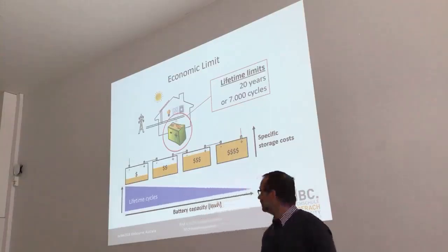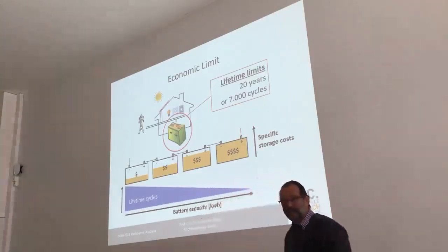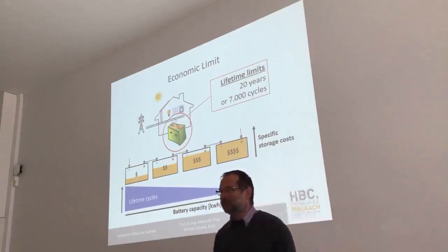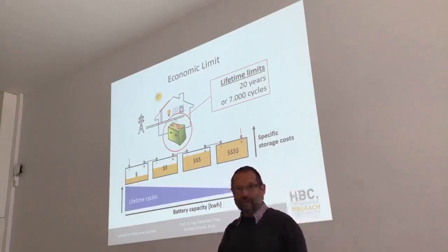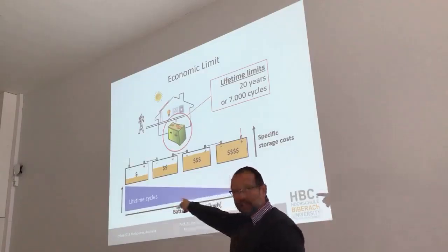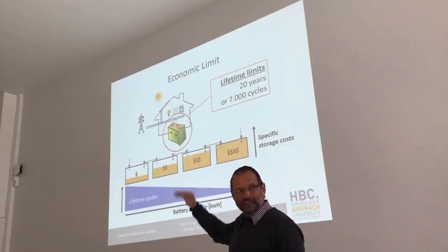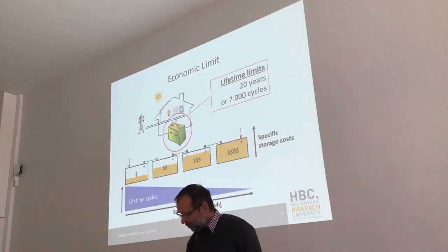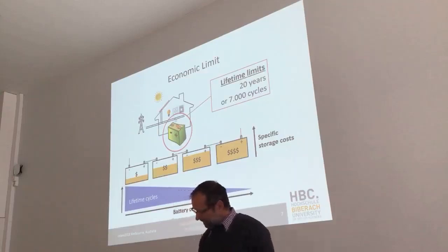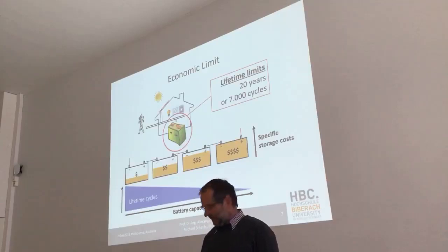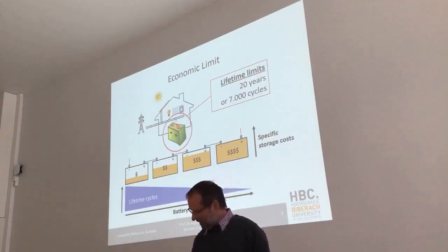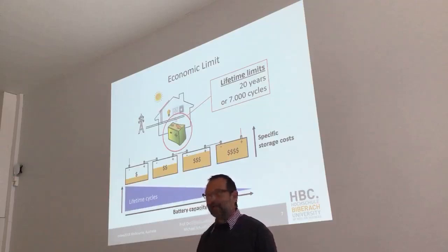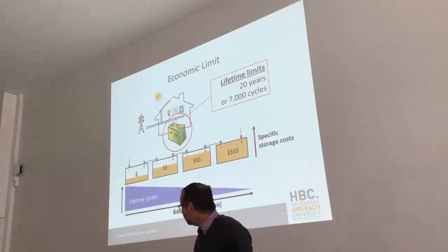Imagine a battery as a sum of battery cells charged and discharged after the principle first in, first out. Then the first cell on the left-hand side passes through much more charging cycles than the last cell on the right-hand side during a given period of time. Since the economics of each battery is influenced by the real charging cycles of each individual cell, the term full charging cycles of the last battery extension is introduced here.